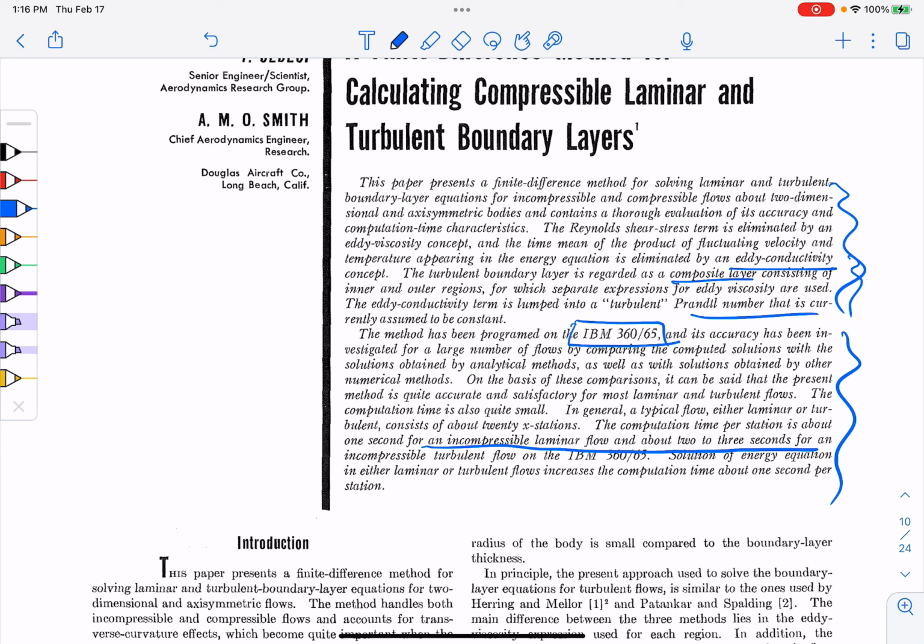That's pretty amazing, because in the class that I teach, Introduction to CFD, for seniors in aerospace, we use a code called SU2 here in the year 2022, and we might run that code on a flat plate boundary layer using the same number of grid points as Cebeci and Smith. And so we're solving the full Navier-Stokes Reynolds-averaged equations with a 2-equation turbulence model.